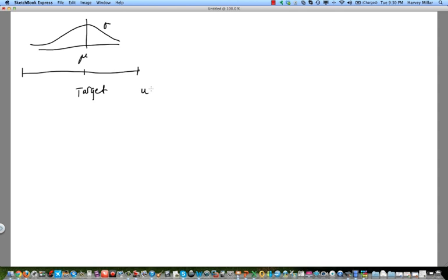So the last thing on statistical process control that I want to talk to you about is a concept called process capability, which is that because the output from a process is random, if we're thinking about a manufacturing process, sometimes we wonder whether or not the process is capable of delivering according to some specs. So let's just say this is the output from the process. What may happen is that we could specify what we call tolerance limits. So this is a target that we want to achieve, and then we have what we call an upper tolerance level and a lower tolerance level.